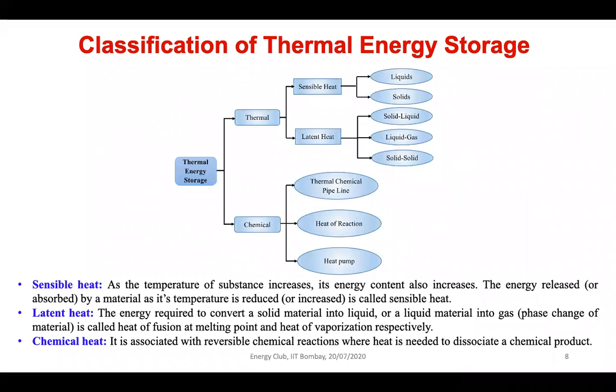Now, different types of thermal energy storages are there, and I will briefly describe all of them. Mainly, these are classified into three groups. One is sensible heat storage, second one is latent heat energy storage, and last one is thermochemical storage. Sensible heat energy storage is well developed, very easy to operate and very easy to design, and it can be useful in many places. Whereas latent thermal energy storage is slightly more complicated compared to sensible heat storage as well.